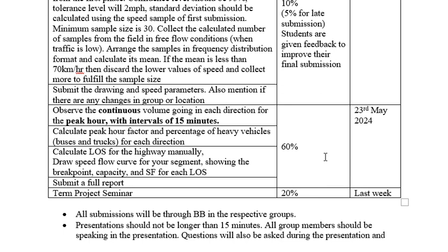Okay, third task. You will collect volume data, meaning the number of cars, the same thing which you did for 15 minutes earlier. Now you will do it for a longer time in the peak hour. I believe you know what peak hour means. The peak hour is the rush hour, when you hate being on the highway, that hour. And it can differ.